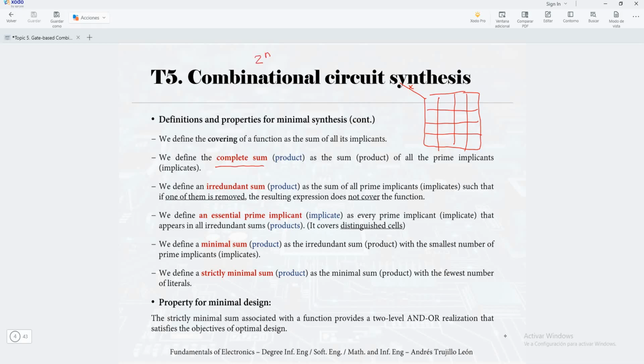So we can link this rectangle or square with a product term. Remember that we used the variables that don't change across the allowed group of ones to form the product term. The variable is going to be non-negated if it's 1, and complemented or negated if it's 0. I'm using negated and complemented as synonyms. So complemented is just a negated variable, in case you didn't realize.